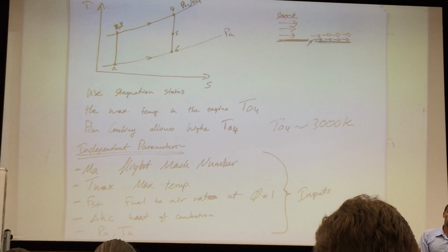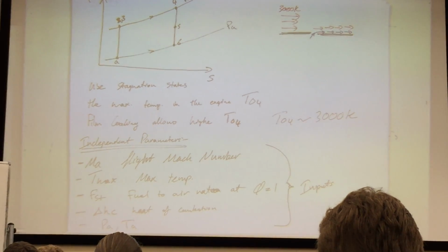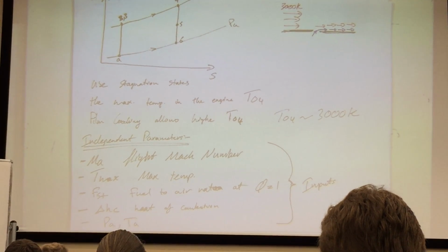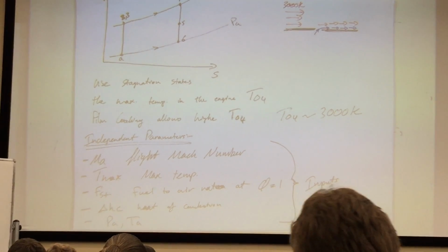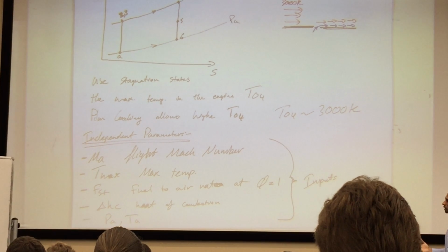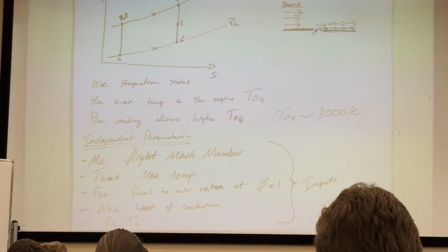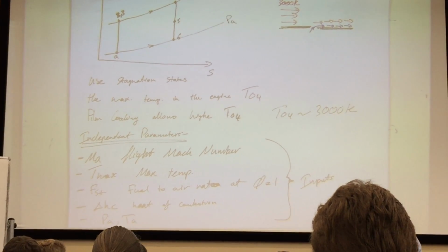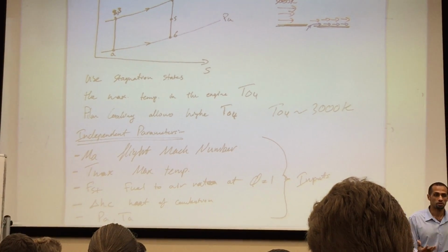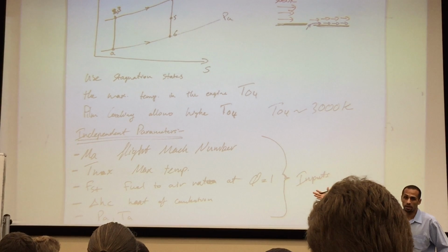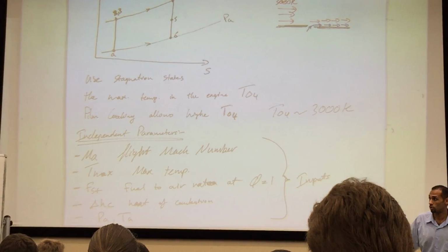Tmax, you control through your materials and your thermal cooling throughout the whole engine. Most likely your combustion temperatures are way, way hotter than the materials that you're ever going to use, and that's the challenge that we have today. We can generate more efficient engines in combustion-based engines. The problem has always been Tmax. You're limited to how much temperature you can really have in there.